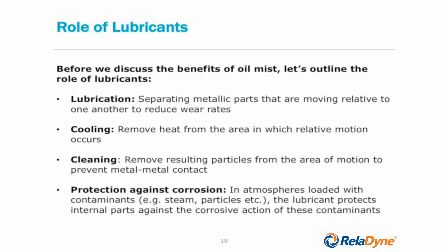And finally, of course, the lubricant, if it's properly selected, is protecting the parts against corrosion. In an atmosphere that's loaded with contaminants, for instance, steam or particles, dust, dirt, the lubricant protects the internal parts against the corrosive action of any of these contaminants.